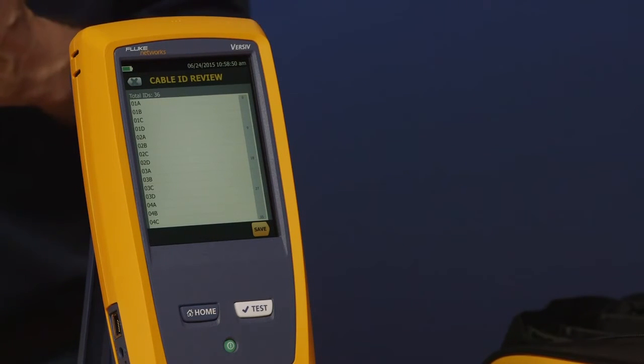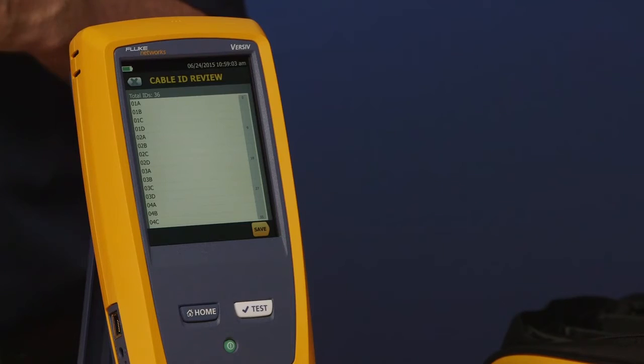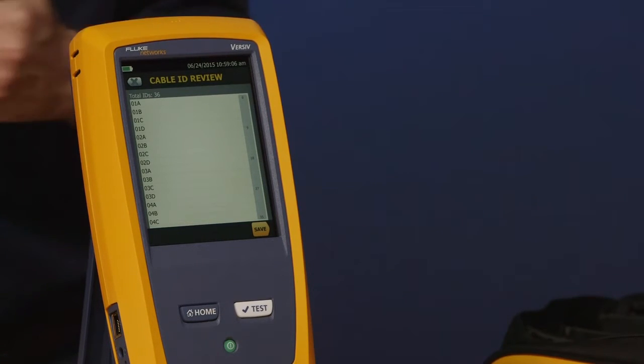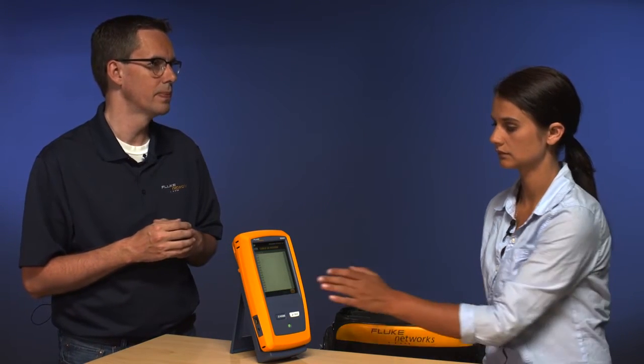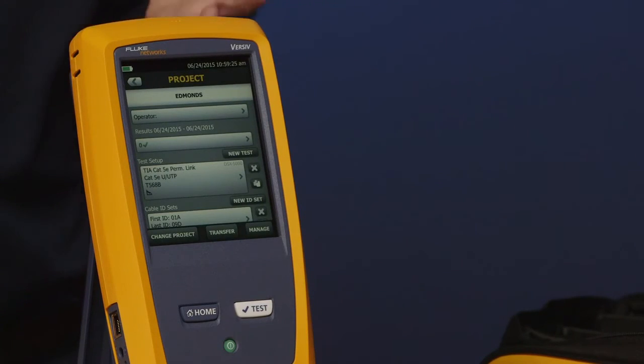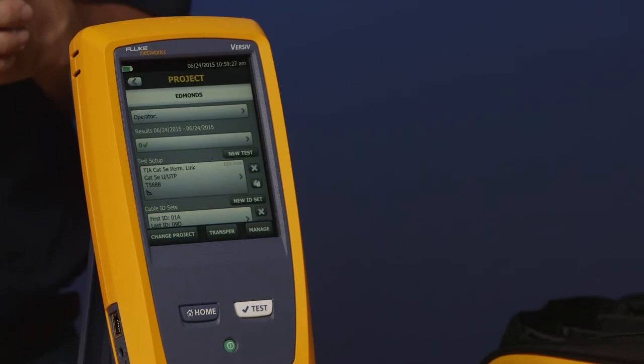So here you can actually review your cable ID scheme. And what you'll notice, taking advantage of this, is once I get to 01D, it doesn't jump to 01E. Because you told it the last digit is a D, it's smart enough to figure that out. Now this is very useful if you're doing an installation with quad faceplates, for instance, or you're doing a fiber optic installation where every ID is alternating between A and B. This is a way of really improving your work efficiency. So we're good with this, so go ahead and tap save. That's our setup configuration done. So go ahead and hit the home key for me.